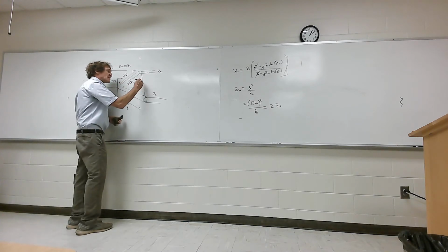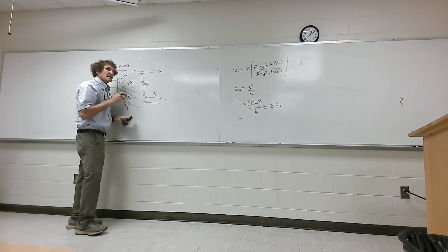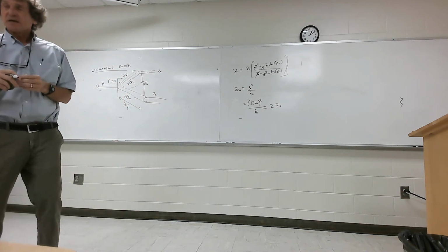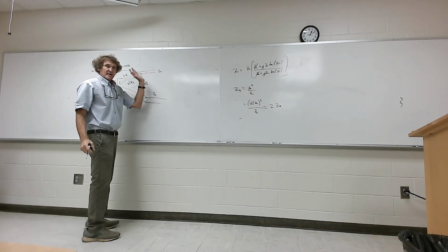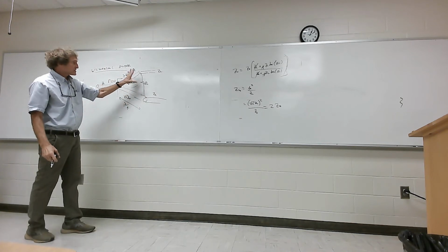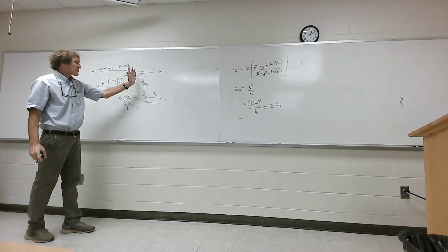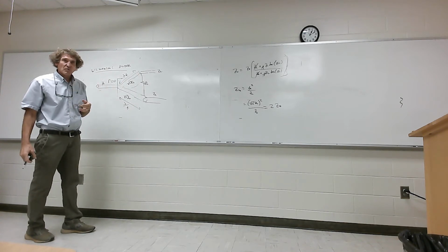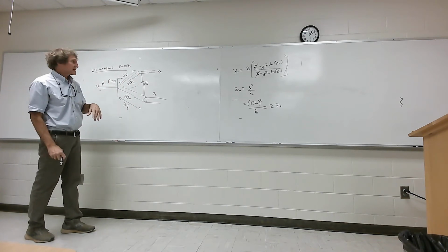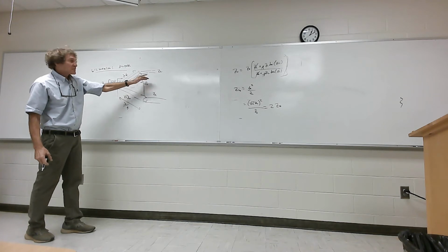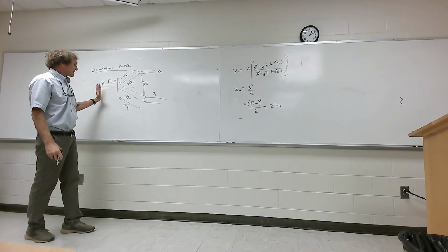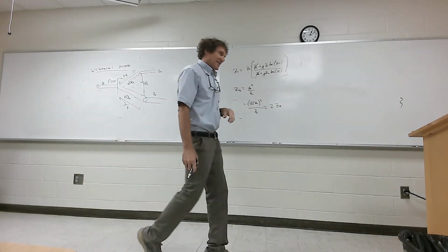That resistor right there is a long story. There's 2 R naught in that. That basically is there for power problems when you're going to have loads out here that reflect back and stuff like this. Without getting into all the details, this thing will basically minimize the amount of reflection that gets back into the transmission line portion. But there's a whole lot to be said about this that I can't say here. Just realize this resistor, ideally you don't need that. It shouldn't matter. But it's there basically to prevent some reflected energy from getting back into the sending circuit. And there's all sorts of problems.